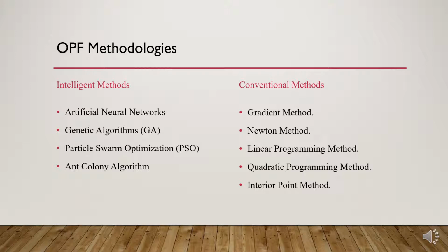OPF has been frequently solved using typical optimization techniques on computer using MATLAB and different optimization toolbox, like fmincon, that has become standard practice to solve a lot of optimization problems. This toolbox from MATLAB has several algorithms with options for Hessians, including fmincon trust region reflective algorithm, fmincon active state algorithm, and fmincon interior point algorithm.